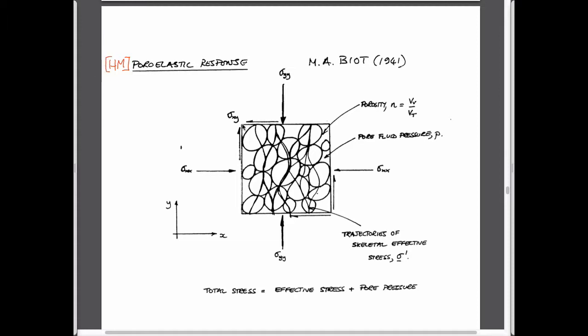And the essence of this is that if you take a bag of marbles, which might happen to be some solid grains and some fluid, and you put a bag around it, and then you pull all the extra air out of the bag so you have a nice tight mixture of grains and fluid and only that, and you try deforming it, what you'd find is that as you try and deform it, because water is relatively incompressible, you get no particular volume change because the fluid that's present in the pores doesn't allow that structure to deform in any way.